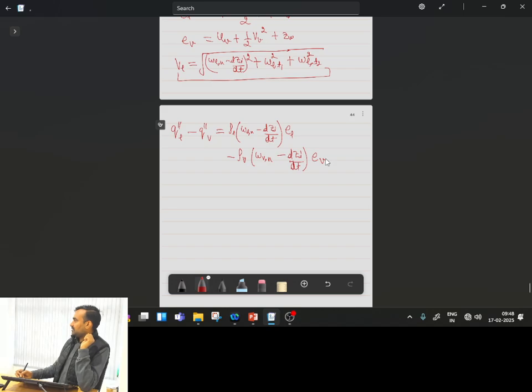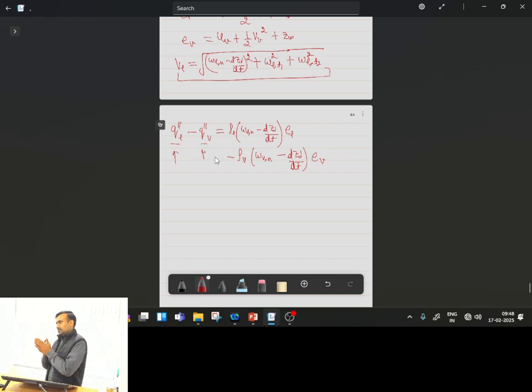All are clear with this point? So here we will have an energy balance at the interface. Now I can assume that near the interface, the interfacial layer, because of the no slip condition, has very little interfacial slip. Then close to the interface I can approximate the heat flux in terms of Fourier's law, assuming that the temperature gradient is known to us.